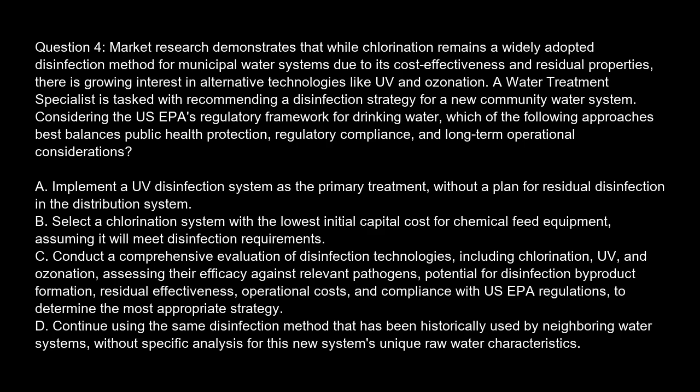Option C. Conduct a comprehensive evaluation of disinfection technologies, including chlorination, UV, and ozonation, assessing their efficacy against relevant pathogens, potential for disinfection byproduct formation, residual effectiveness, operational costs, and compliance with U.S. EPA regulations to determine the most appropriate strategy. Option D. Continue using the same disinfection method that has been historically used by neighboring water systems, without specific analysis for this new system's unique raw water characteristics.